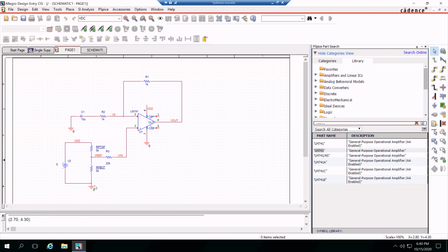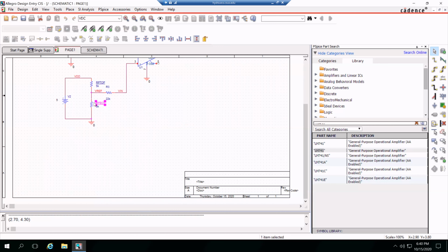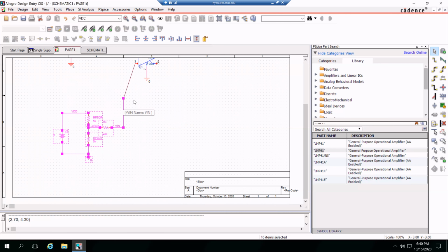If the wiper goes all the way down to the ground, same thing. It's just 22K plus 0. So right there, you know your upper and lower impedance value bounds if you're looking down through here, because this impedance is going to be a function of the resistance coming down here, right? Why is that important? Okay, I'm going to shift this down. Hopefully this works for me, because I want to show you one more thing, because you have one more calculation, one more pole frequency that they ask you about, right?